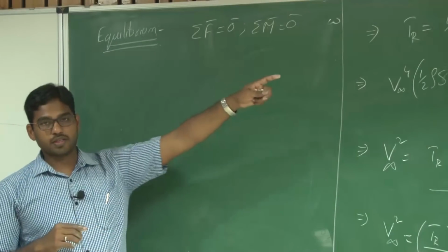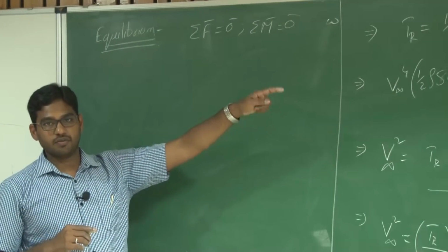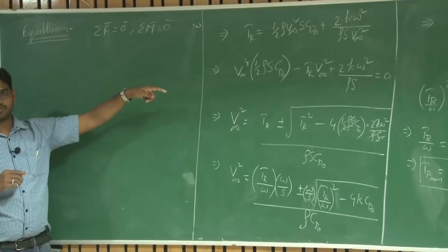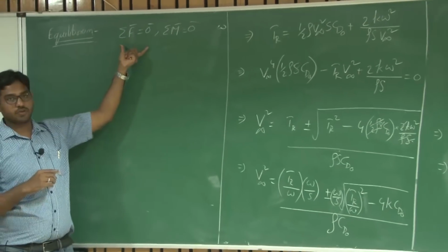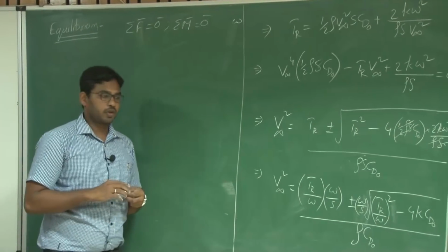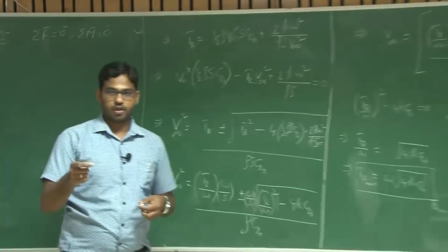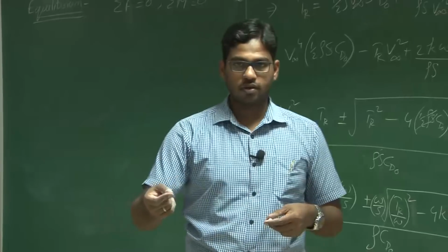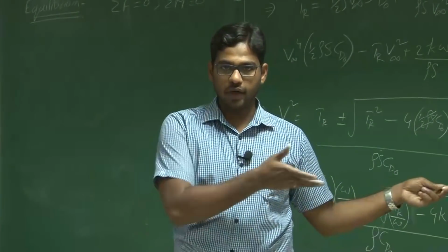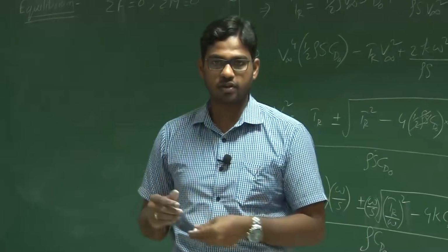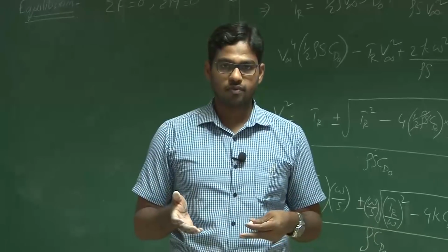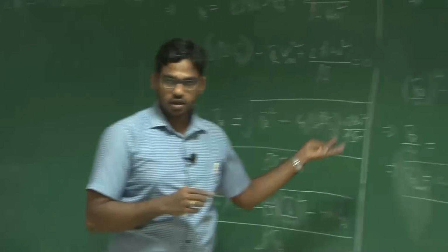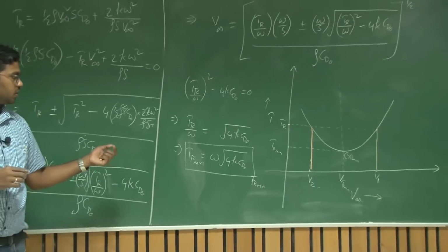Now we can say cruise is a steady and level flight where there is a constant velocity, which is equal to equilibrium. So if you are flying at different velocities, that means you are producing different thrust required from the engine. Ultimately you have to supply that thrust required to the system, to the UAV. So that thrust required needs to be generated from the engine.